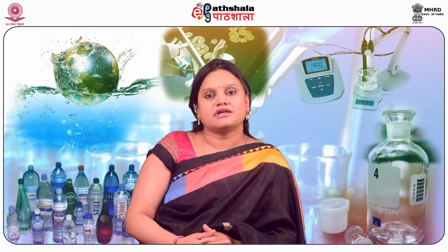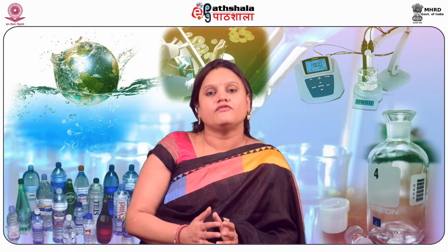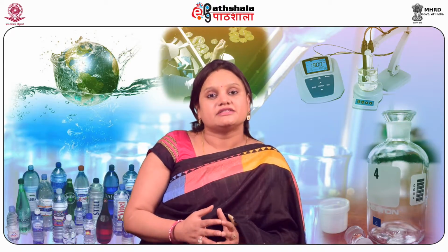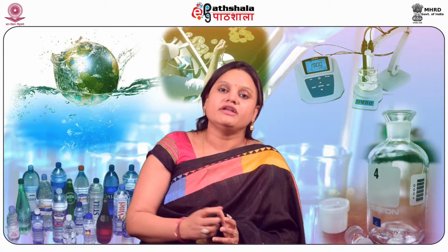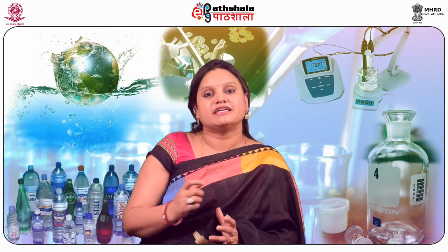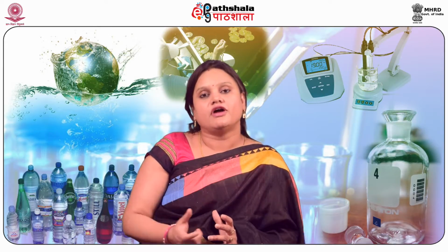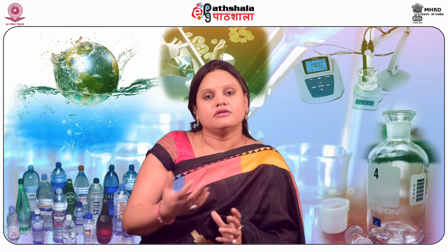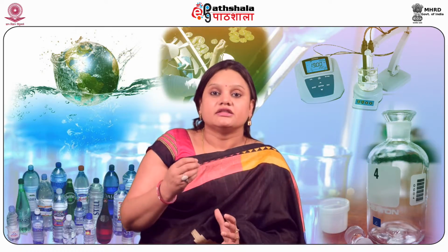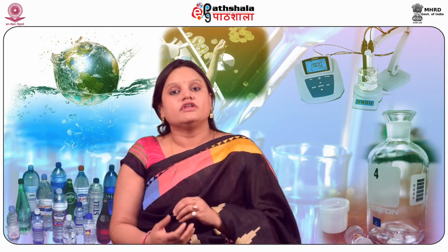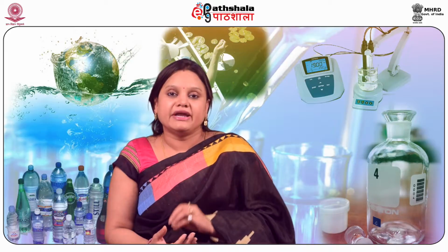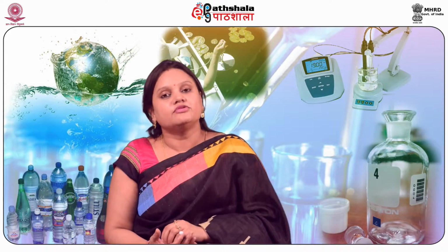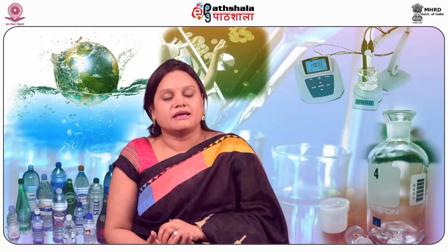The samples are representative of the whole water body that we want to analyze. The sample should be small in volume, but it should be representative of the whole water body, whatever it could be, a lake, a river or potable water. The integrity of the sample should be maintained from when we take the sample until we have analyzed it.